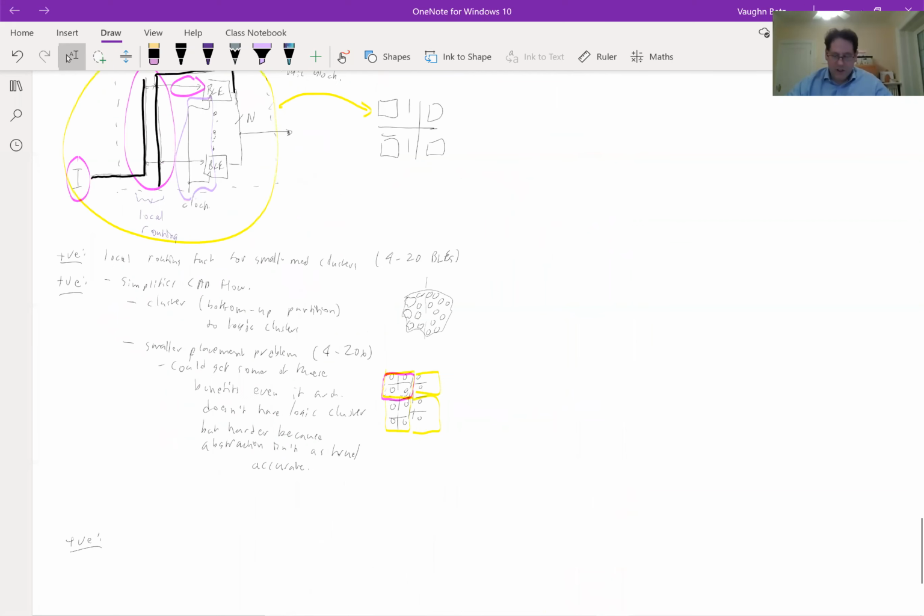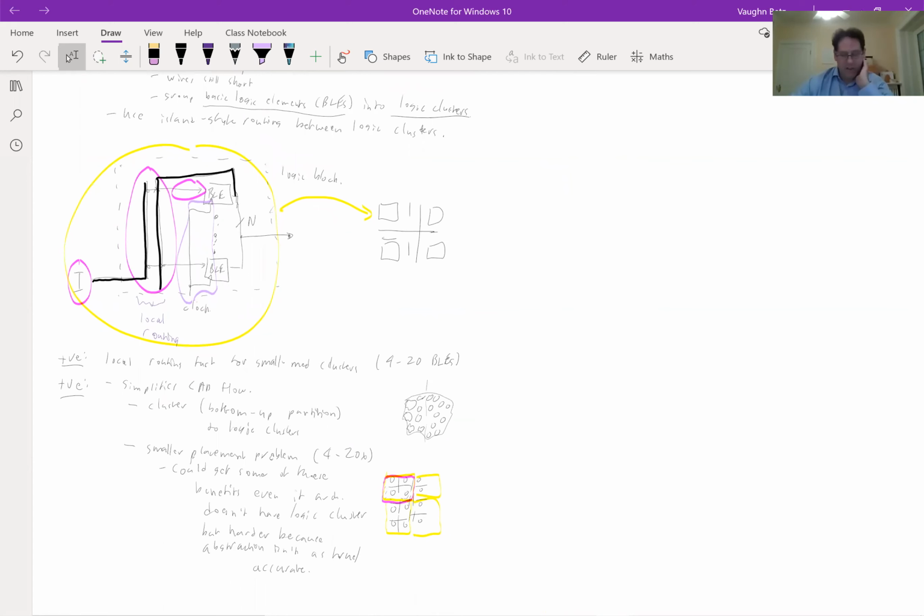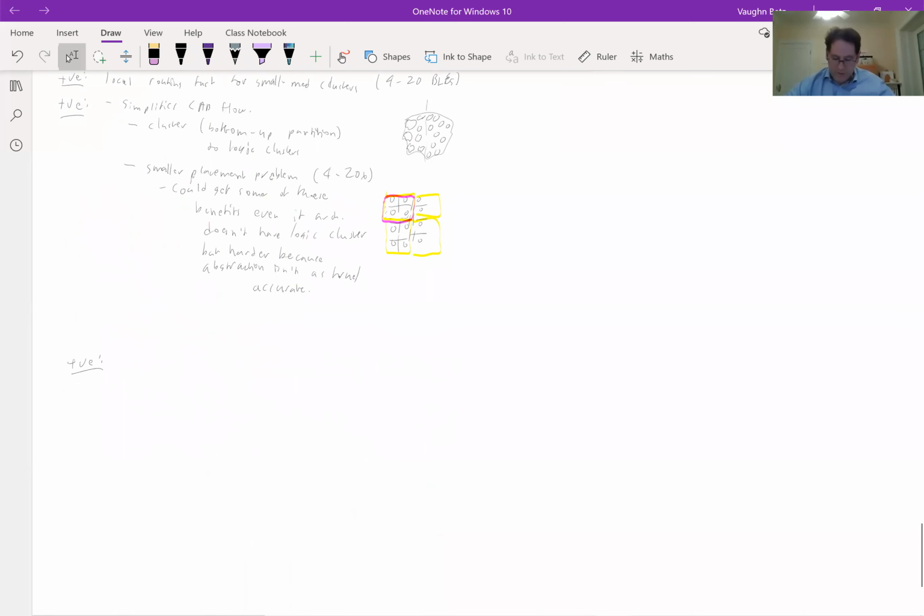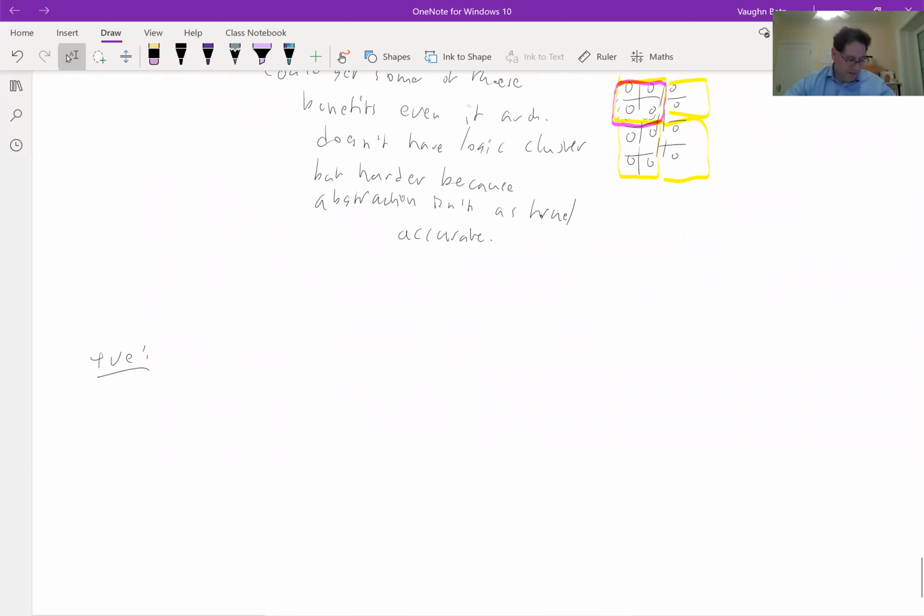So basically, the clocks need less flexibility than the general inputs to my basic logic elements. Every input to a LUT could be different. You're doing different logic functions, but it's rare; all your flip-flops are going to share clocks a lot more. So basically, this becomes a way to share resources that don't need as much flexibility.